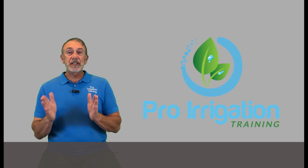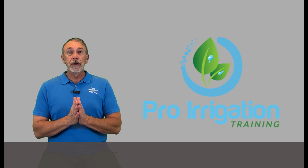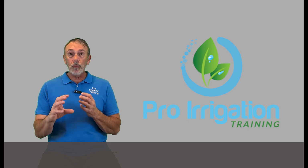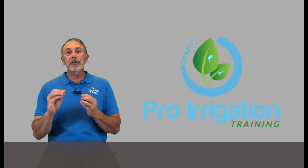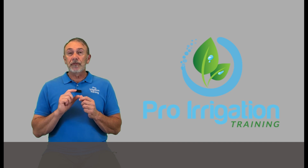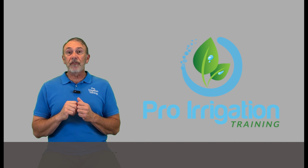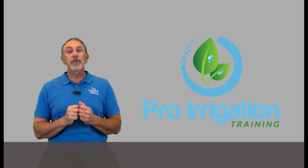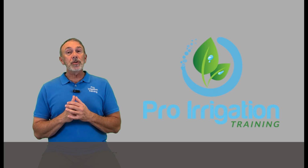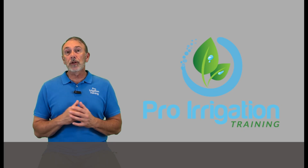And we've also spoken about the relationship of these, that they're all intertwined, that if you take the same setup and you put more pressure through it, it's going to push more water, meaning it's going to have more flow, more volume of water passing through the pipe over the same amount of time. But that also means that the velocity necessarily has to go faster. The water has to go faster through that pipe to match that increased flow. And it's also going to give you more friction loss.